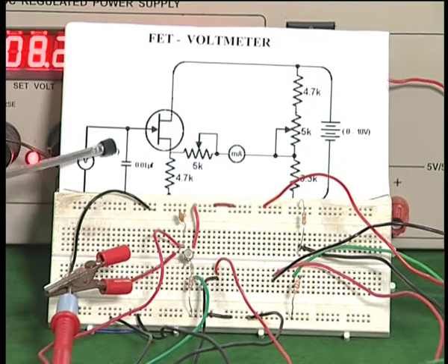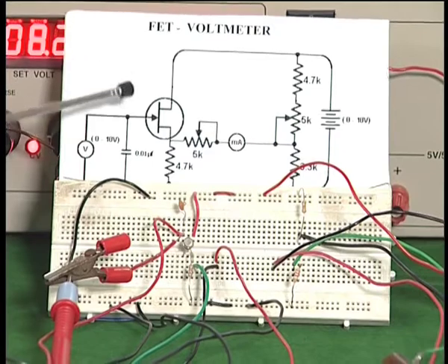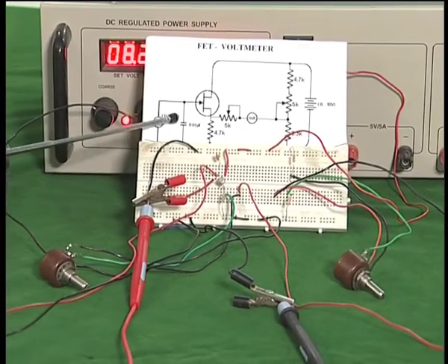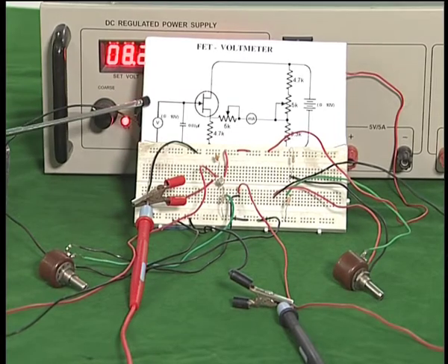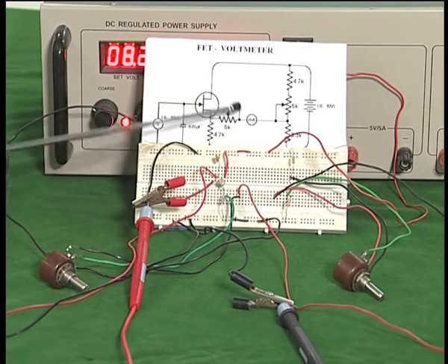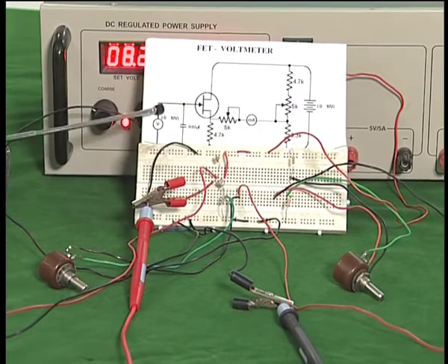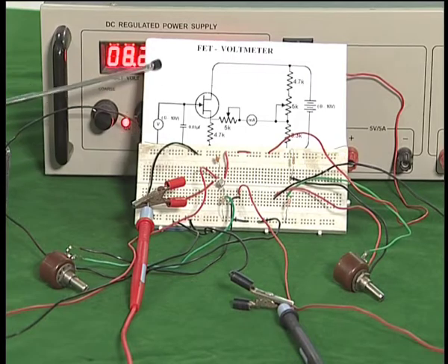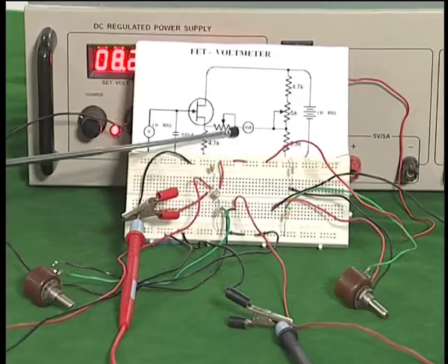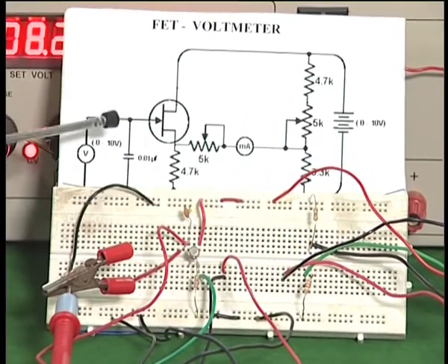Now instead of applying 1 volt, I can put a potentiometer here and make it 0 to 1 volt. I can reduce the voltage I apply here to 1 volt when I apply 10 volts. That means I can have a 10:1 reduction here, so this voltmeter will read from 0 to 10 volts. If I make a reduction from 100 to 1 by having a number of resistors here, then I can have this current meter read up to 100 volts. So that is what is normally done in a multimeter.